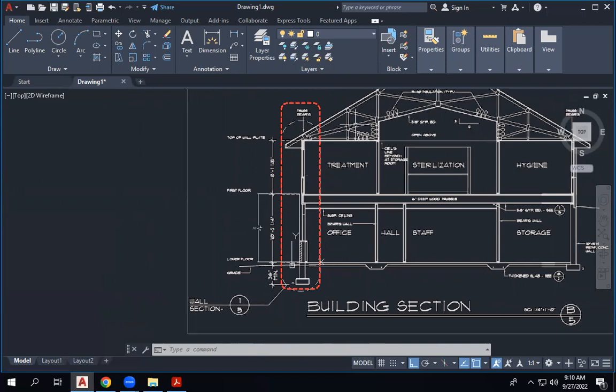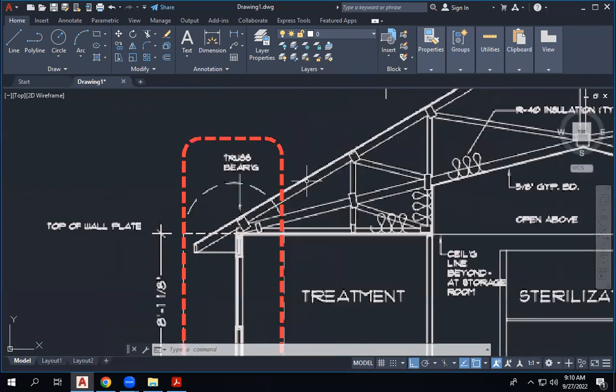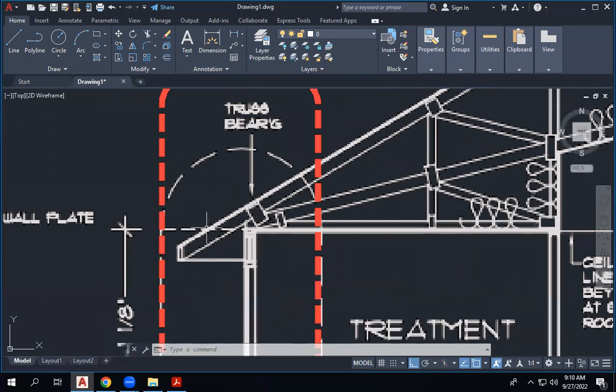See here, now in the roof, there is this purlin. Can you see this purlin here? This line is in elevation. It's not cut. The only section that will be cut is this one. No, this is the rafter, this is the purlin. So the purlin will be cut and the rafter will be in elevation. So we will use the 0.2 line for this one and 0.35 where it cuts. So we have two line thicknesses.